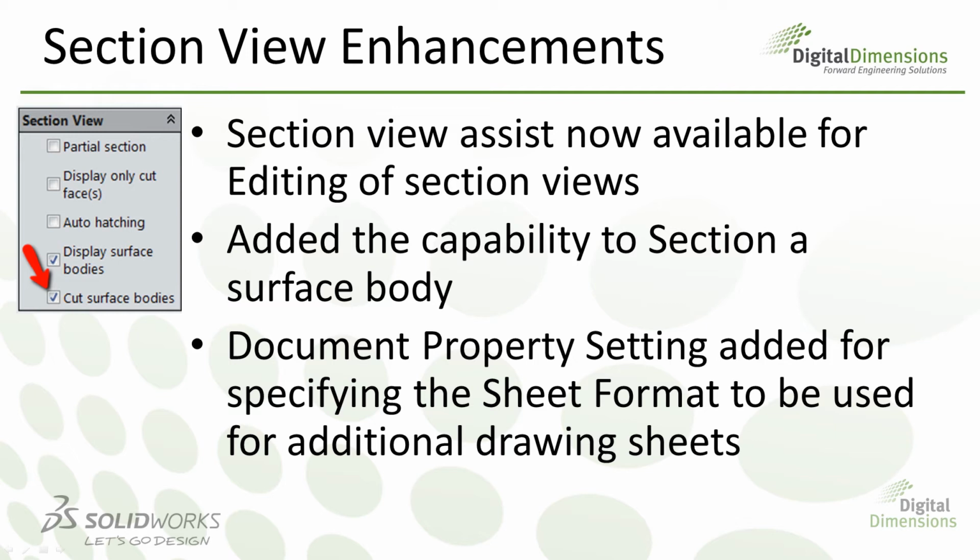But if you created this section view in 2013 using the section view user interface, in 14 you'll now be able to edit those section views with the section view assist. In addition to this, they've added the capability to now section a surface body. Now, this was a limitation in previous releases.